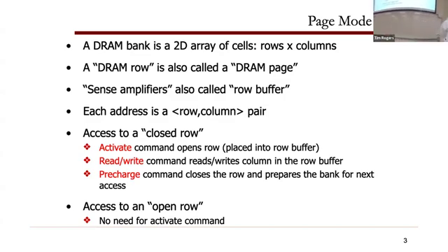There's these things called sense amps. Anyone who does VLSI knows these very well. These basically detect very small changes in voltage or current across two lines to try to very quickly read out whatever is in the cell. It's analog circuitry, probably the most complex analog circuitry in modern systems that gets used all the time. Sometimes this then gets latched into some sort of storage cell. Sometimes it doesn't. You're just reading the raw output of the sense amps. It doesn't really matter. What matters is that this is called the row buffer. So you bring the stuff down to the sense amps, and whatever bits they're blasting out, that is the row buffer, because that's all of the wide data that you read on this particular cycle.